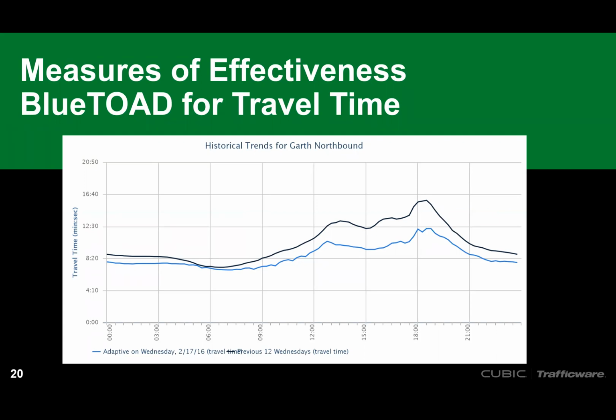A lot of you may be familiar with that. And so you can see here, we have a Bluetooth device that's deployed at one intersection and then measuring the travel time to another device deployed in another intersection, preferably the end of the corridor. And that travel time between those two locations can be graphed as you see here. And it can be done in a before and after deployment to show those two different travel times. So you can see here, one of those is where it was before the study, and then you can see the achievements in travel time after the study.